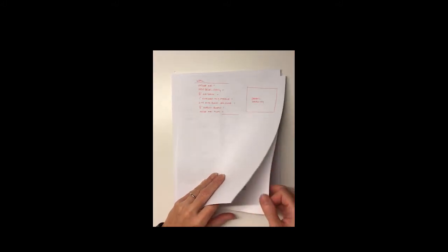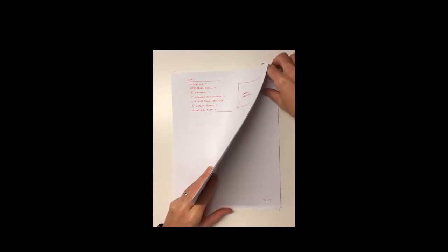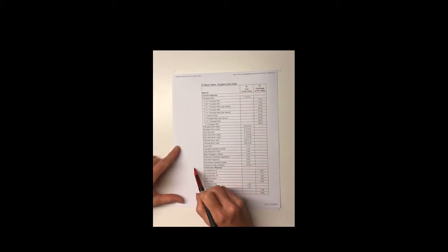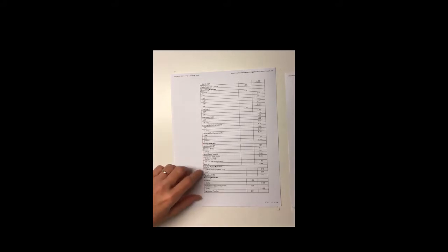And in the handout that I gave you as part of this assignment, you will see some tables, and it is going to have R values for common building materials. So it's broken up into insulation materials being this first section, then a variety of other construction materials. Here you have sheathing, siding, interior finish materials. Then you have roofing materials, windows, doors, and air films as that last category.